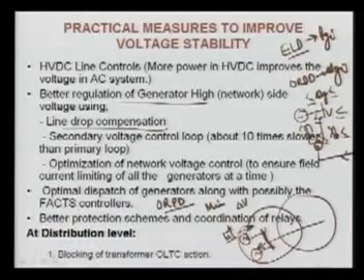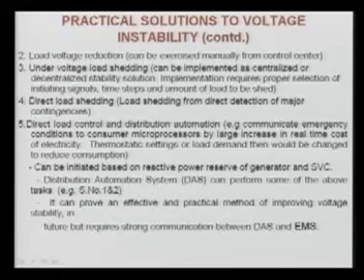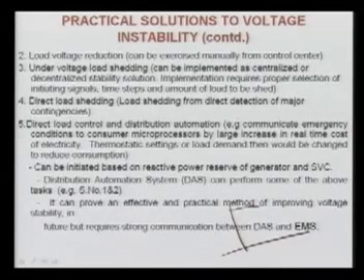To see this, let's suppose here is the PV curve at one tapping, and at another tapping you have another curve like this. If you are operating here and you change the tapping from this point to this, you land here in this negative zone and your system will be unstable.